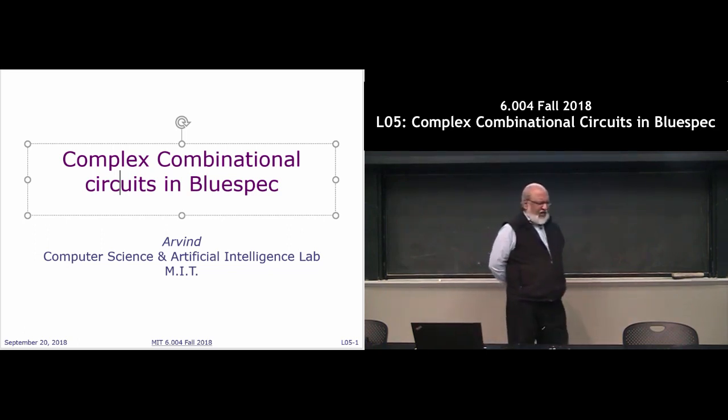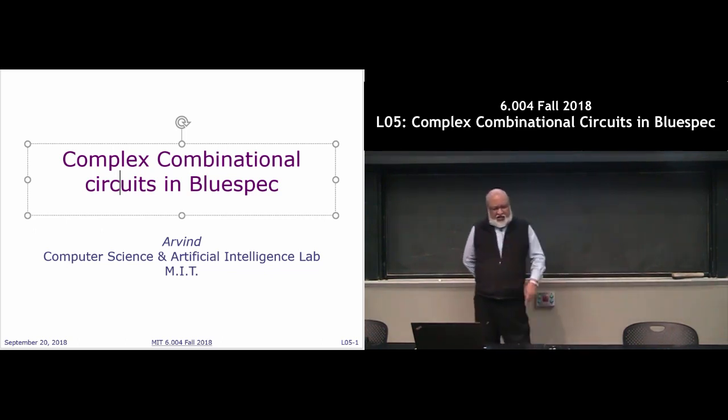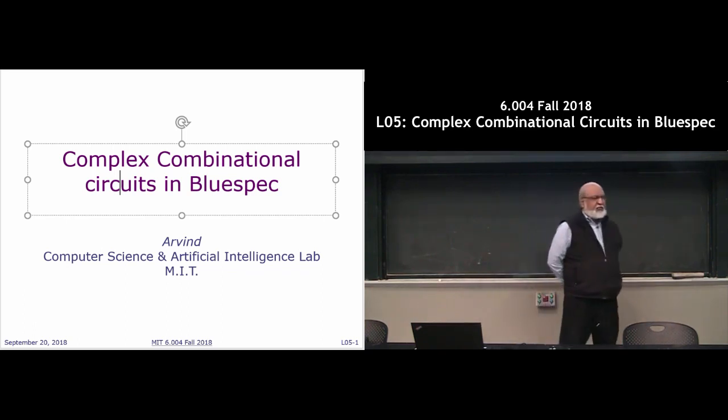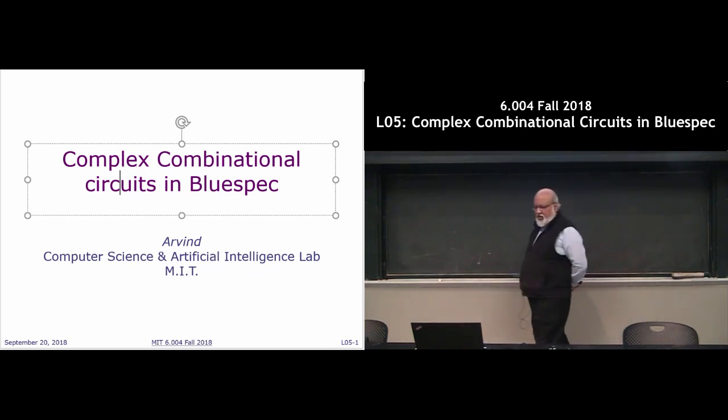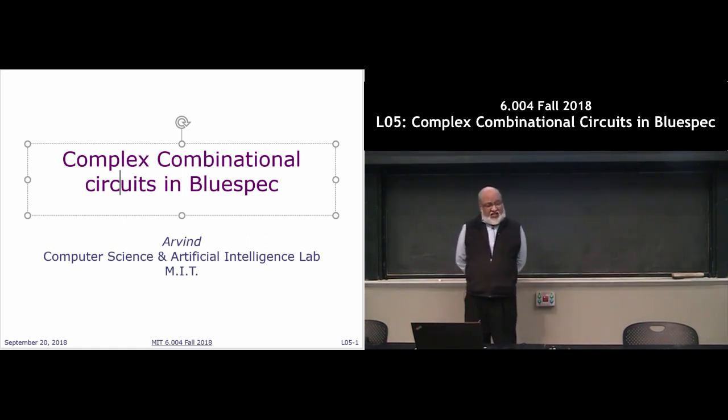Only 3 operators are defined in the types world for doing arithmetic: TAdd, TMul, and TLog, logarithm to the base 2, is also allowed. So if I write bit W plus 1, it's not correct. And if I write bit TAdd W comma 1, then you're getting 1 more.